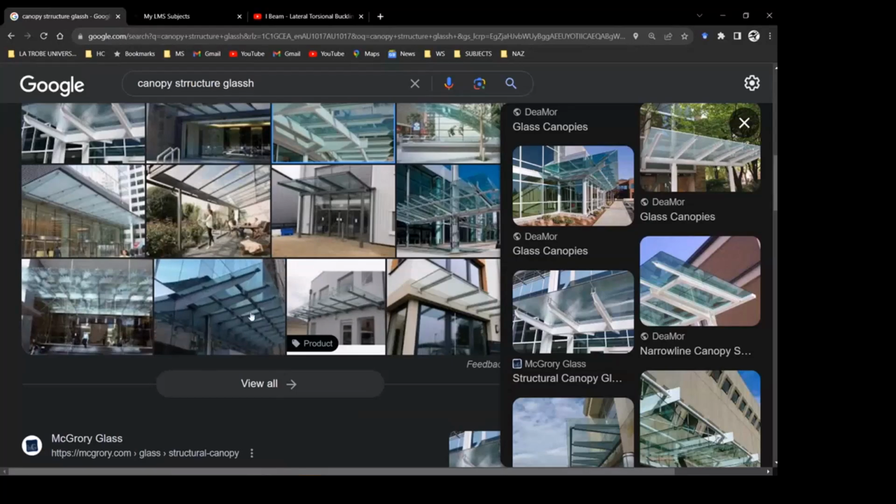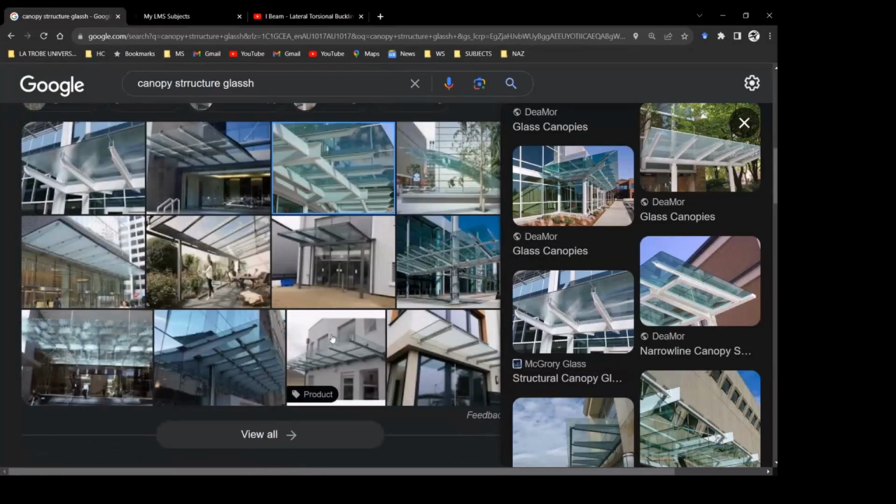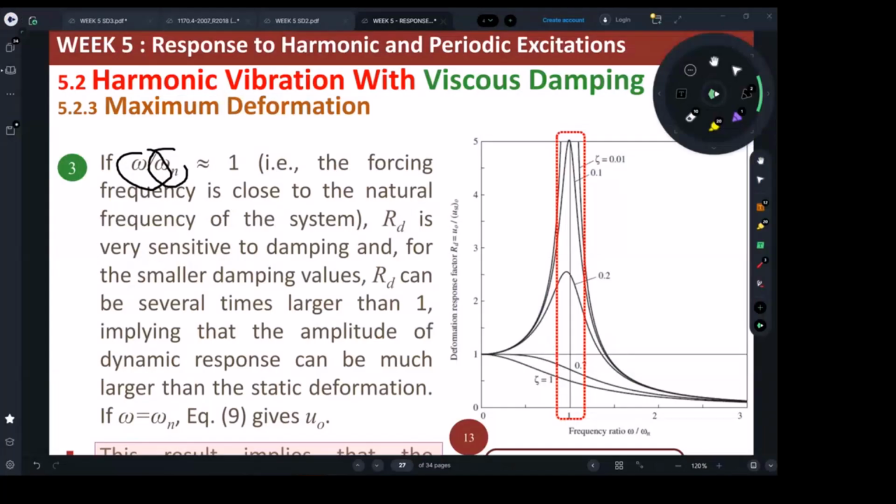So what I'm trying to say, these kind of systems are more affected. If you go and design them, do the calculations, you will find their systems are lying around there, because the frequency from the road, from traffic, or from train or tram lines, can be very close to their natural frequency, unlike a building.